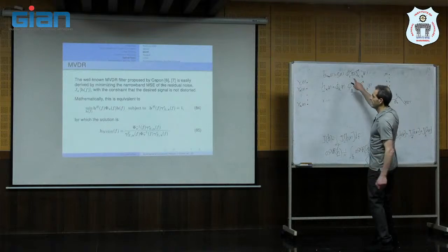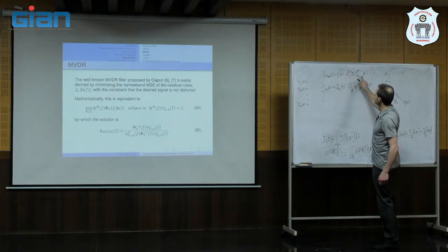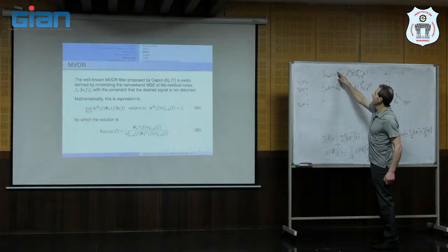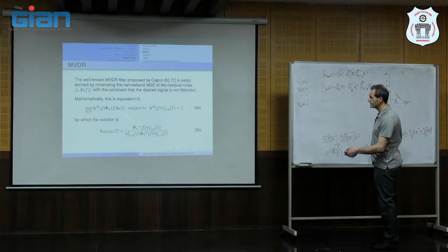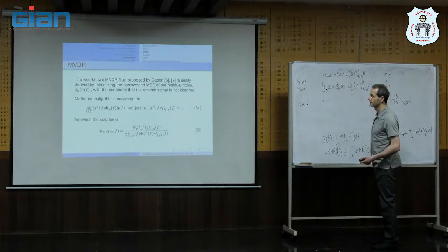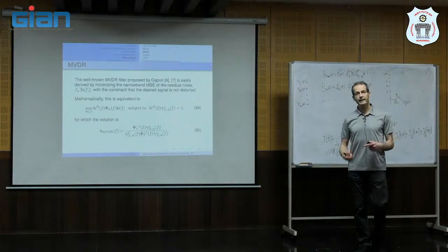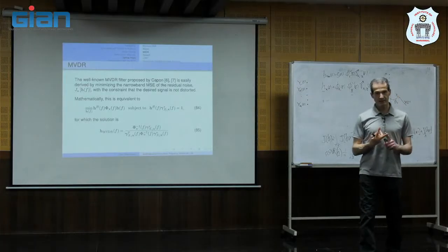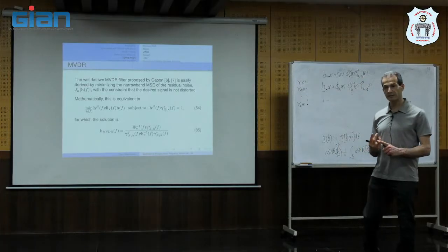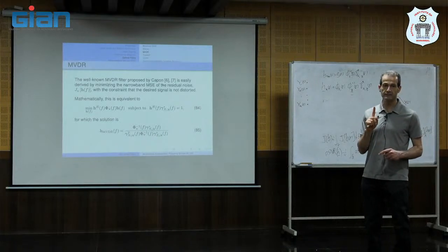See, it's proportional to this. So this value, zeta, the weight, is a scalar. So it's 1 over this. These are the weights. So you see how the MVDR, the Wiener, and maximum SNR are all related. All related for the narrowband.